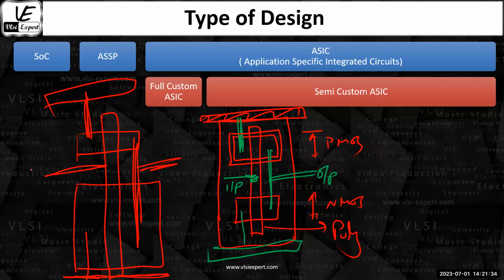But when we are talking about the standard cell, that means something is standard in this particular layout, which may not be standard here. When we talk about standard cells, usually we talk about the standard in terms of the height. So height is going to be the standard, and then we draw the layout. I will explain that part later today itself: what is the meaning of a standard cell and how it is going to help you in physical design. But right now I'm just trying to help you with fully custom.